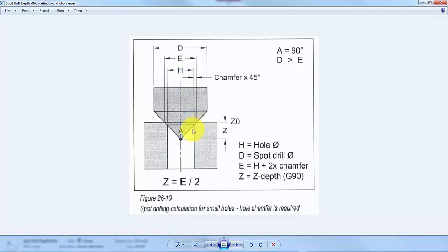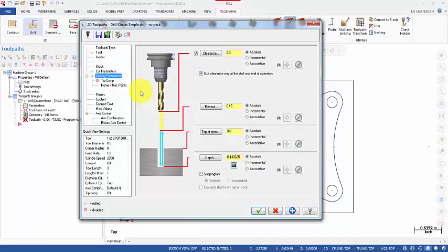If I want to make a countersink, a nice chamfer for the edges of this hole, I have to specify the finished diameter. Normally the finished diameter is less than the tool diameter and greater than the hole diameter. Our hole diameter is 0.25, that's why I chose the finished diameter to be 0.28. This will determine how much chamfer there will be. We are done here. That's all we need to do on this page.